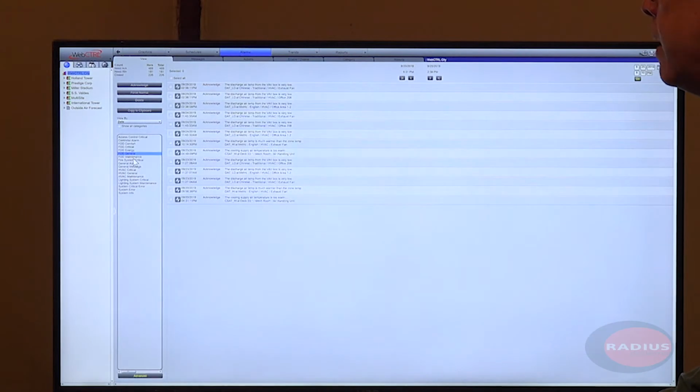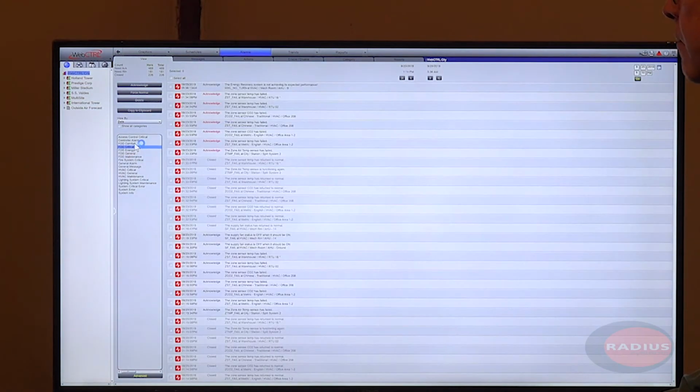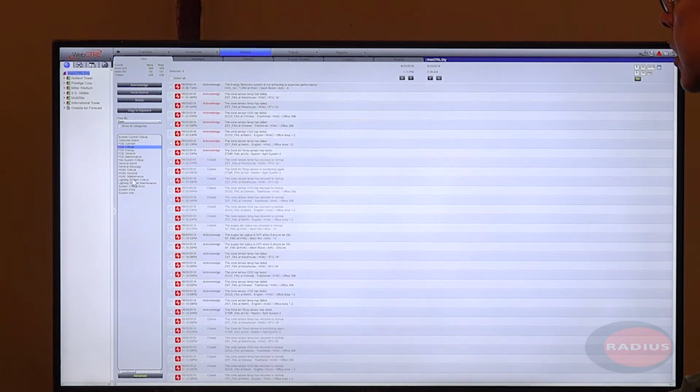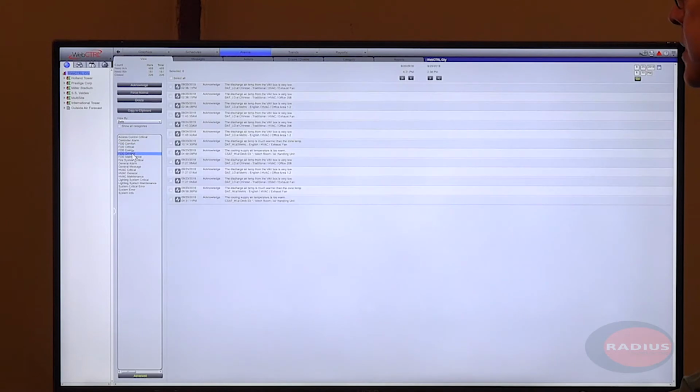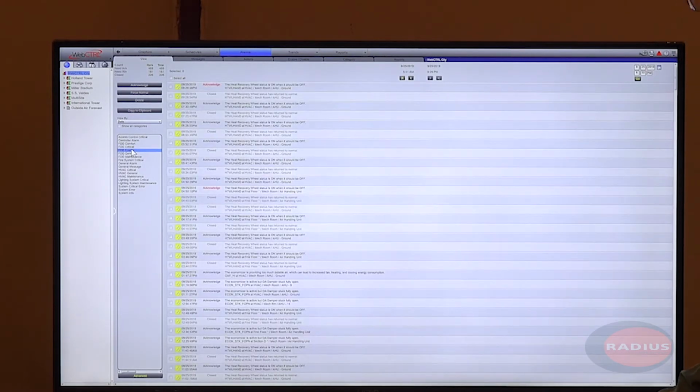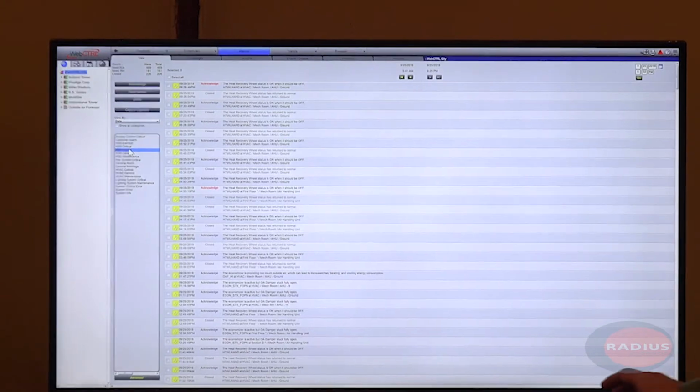I'm going to click one of these and I'll zoom in a minute, but my point was it's good. Everybody does alarms, but it's better if you can categorize alarms by general, by maintenance, by critical, by comfort, by energy, right? Energy consumption, right? So if you've got an energy manager, maybe they're only interested in the energy faults, right? You've got a comfort person, Jimmy Lowe guy you just hired, to make sure it's not too hot in Susie's office, right? Maybe he's looking at the comfort ones, right?